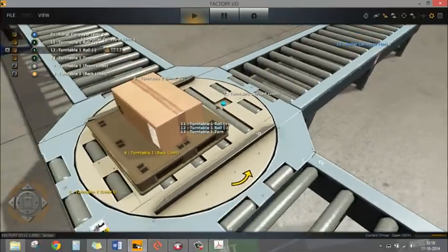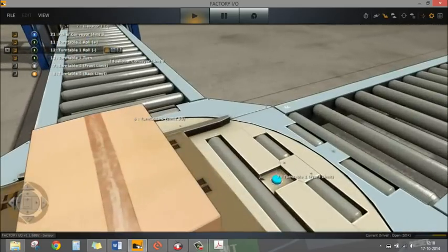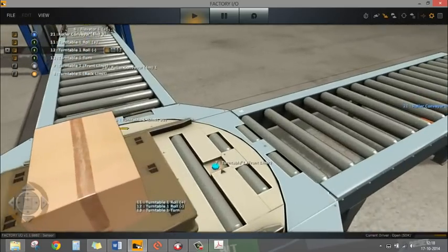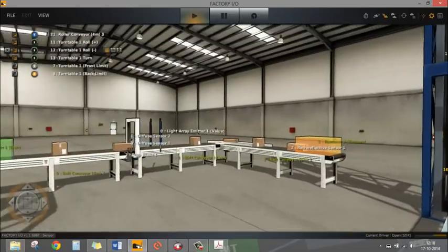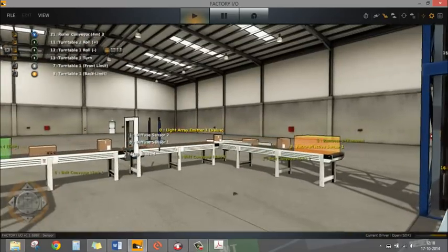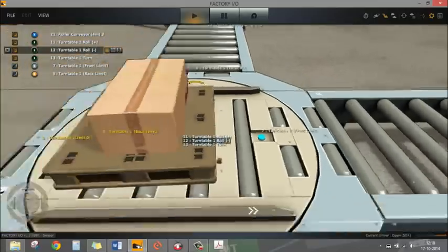Okay, so this was about the capacitive sensor, how you can utilize a capacitive sensor to sense these objects. You must remember this can sense both metallic and non-metallic. And you might be wondering then why we use a diffuse sensor. This is for the same principle. Generally the capacitive sensors cost less than the diffuse sensor.